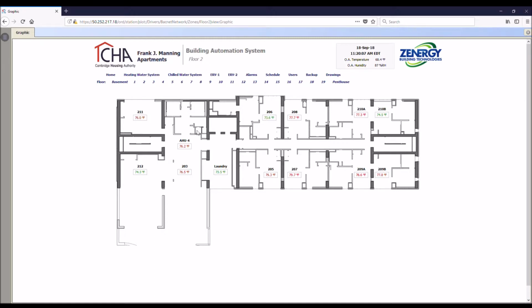On the second floor, most of these space temperature values are coming from that AppStat, except for these three here: the air handler 4, which provides fresh air for this area, rooms 212 and 203. Those are ceiling hung fan coil units that operate pretty much identically to the rest, but the sequence is a little different. They both have exhaust fans that they control, and actually 212 has 2 fan coil units wired to one controller, so they have a slightly different controller with a different thermostat. The same thermostat that air handler 4 has, which is a net sensor.